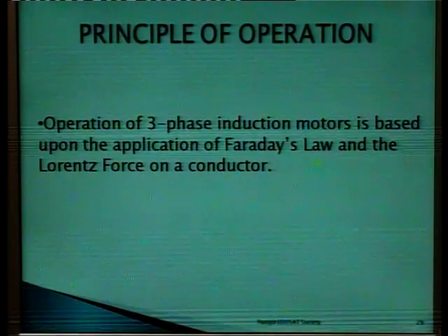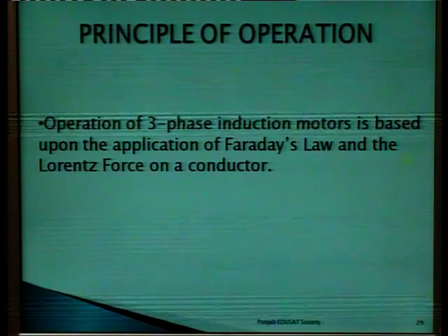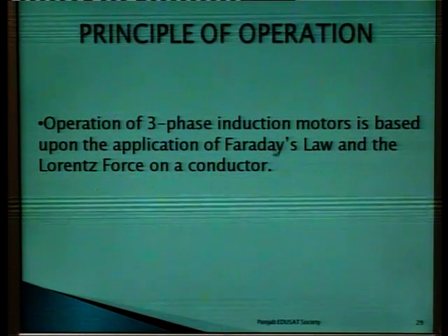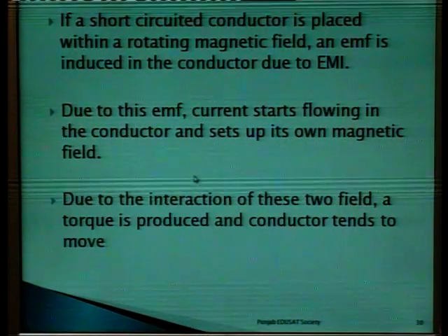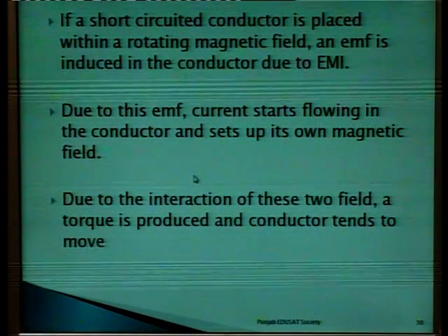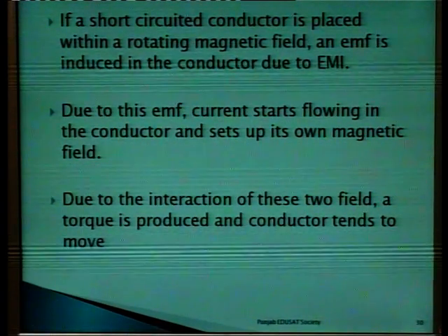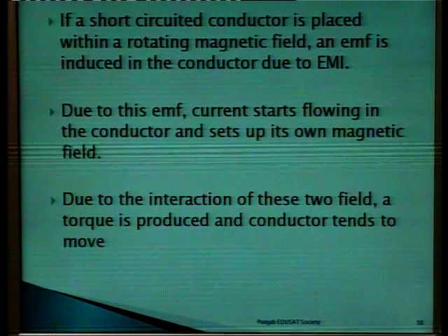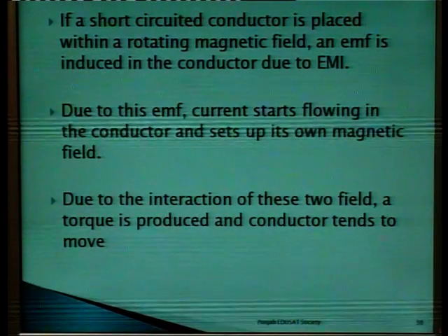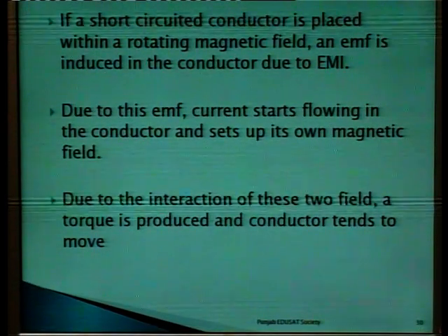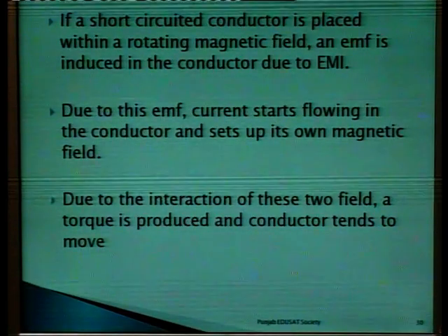Next is the principle of operation of induction motor. Operation of a 3-phase induction motor is based upon the application of Faraday's law and the Lorentz force on a conductor. If a short circuited conductor is placed within a rotating magnetic field, an EMF is induced in the conductor due to electromagnetic induction, and due to this EMF, current starts flowing in the conductor and sets up its own magnetic field.